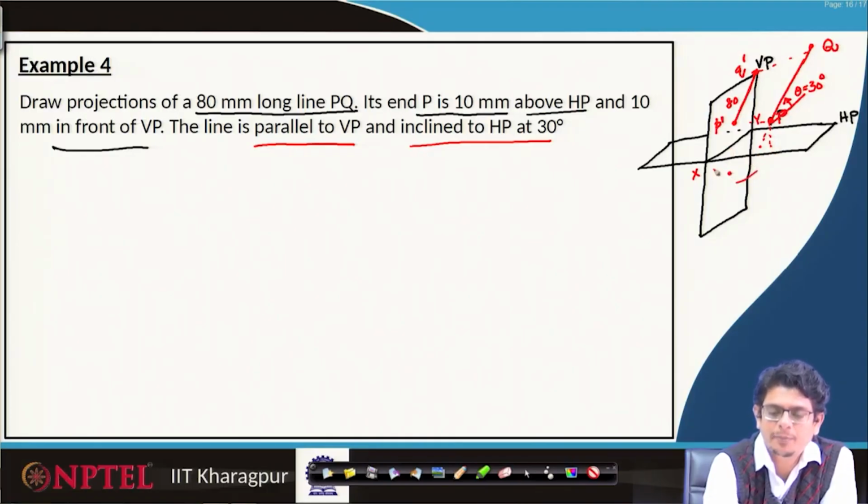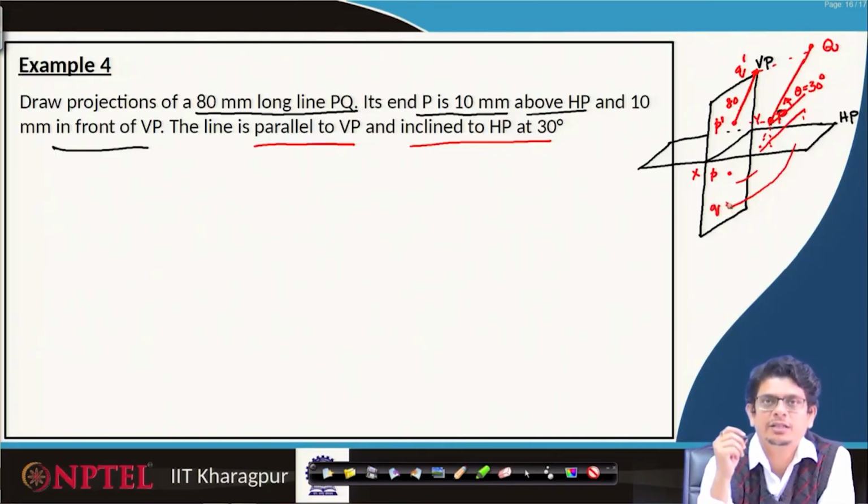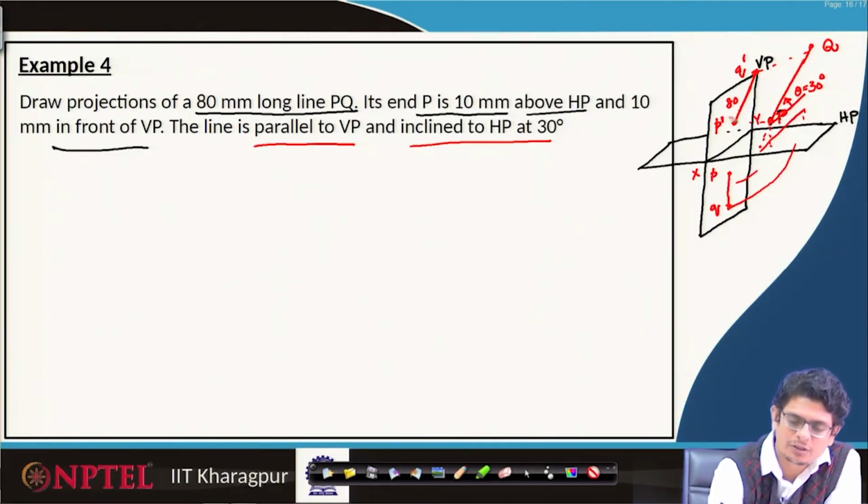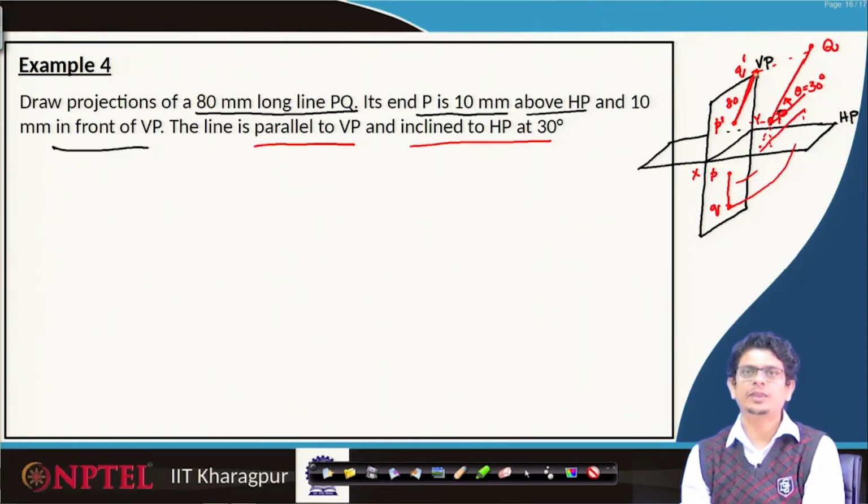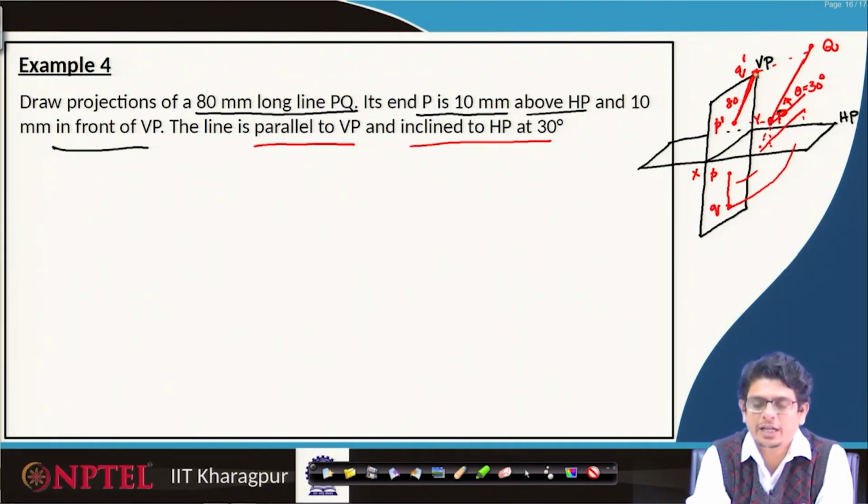So, somewhere here P. Similarly, project this Q all the way down onto that plane. So, it appears in that way and rotate it by 90 degrees, so that we will get Q. Then join PQ, join P prime Q prime. This is the way we should really construct a line on this plane.